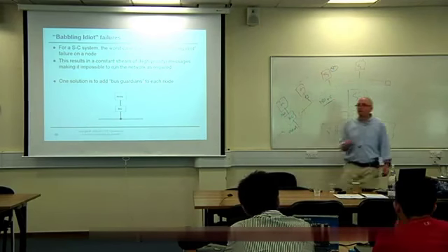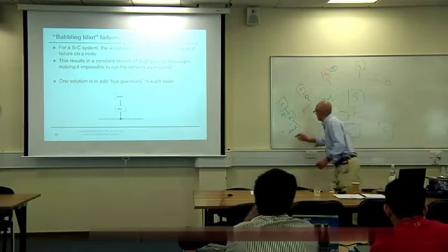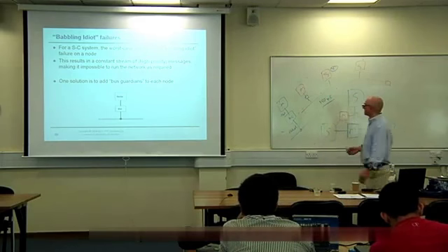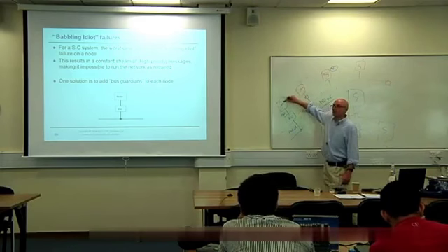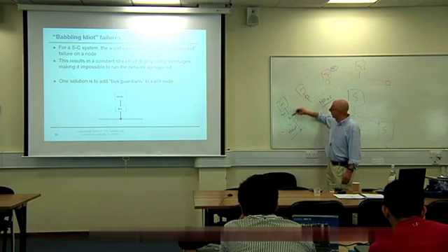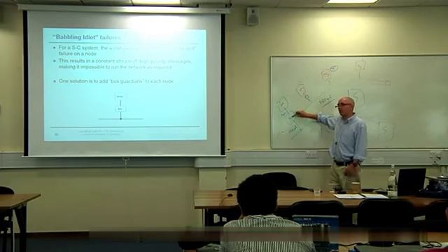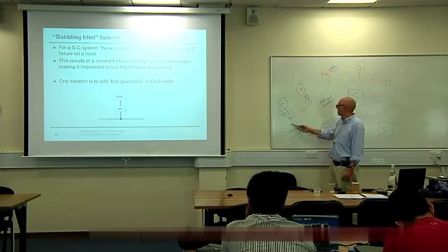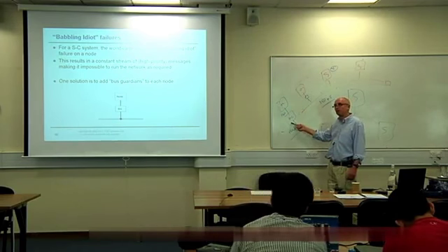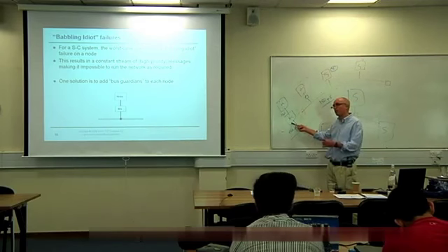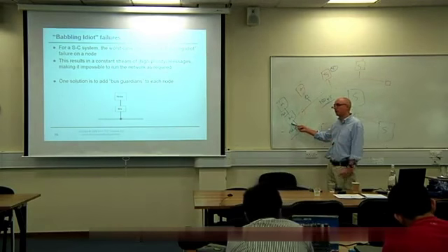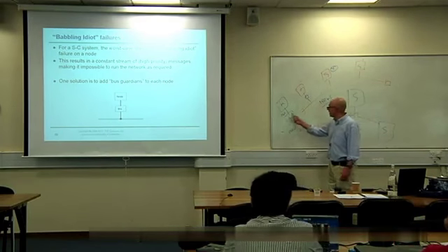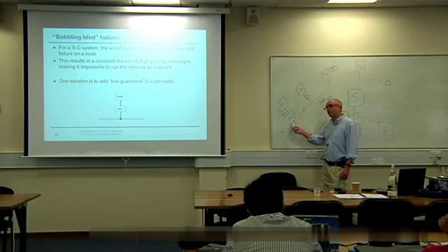We've got another network coming out of it, and it's this second one at the other side of the bus guardian that communicates with the rest of the bus. The argument is that this is complicated code. All this has to do is just record the schedule. So basically this simply needs to know when this guy is allowed to talk on the bus. And it only effectively opens a connection to the bus at those particular points in the schedule. And otherwise there is no link between that and the bus. And the idea is that that's very simple, easy to reproduce.